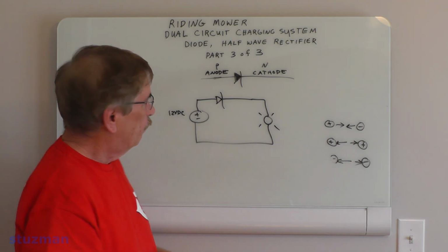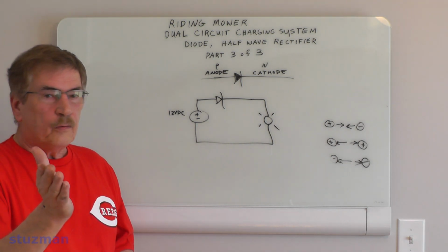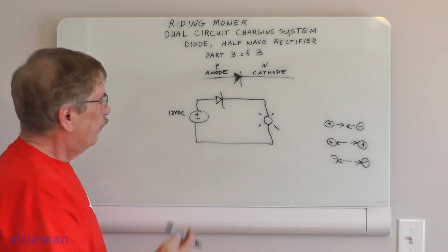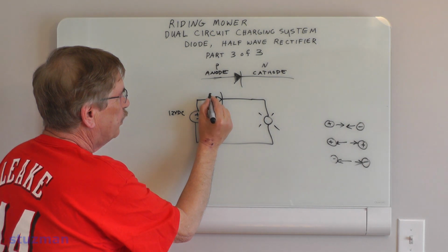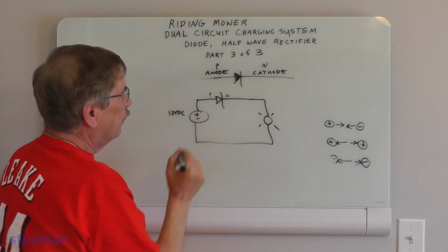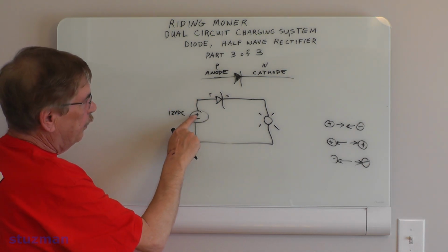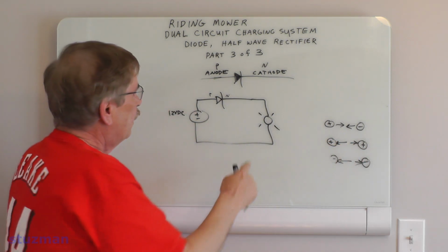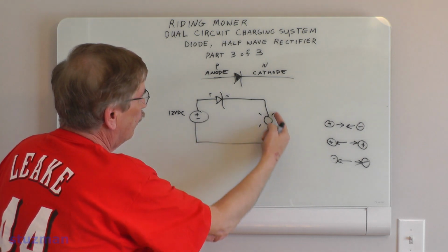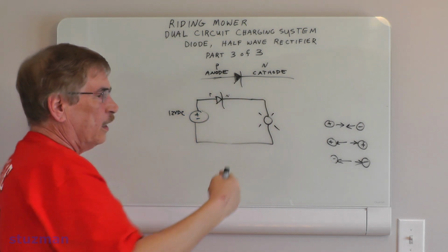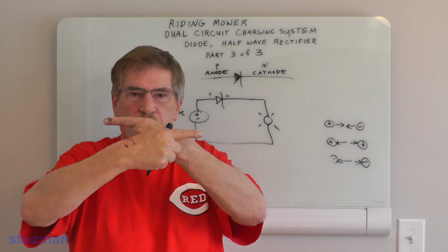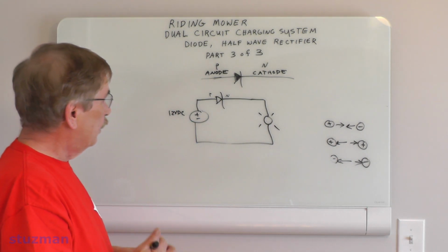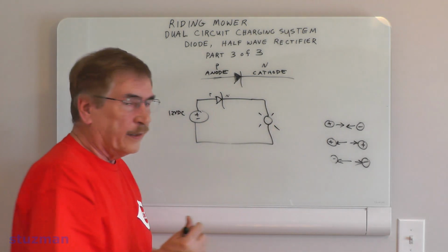All right. Now you can look at that. I know right now, is that diode turned on or is it turned off? Remember, here's our anode. Remember the anode is P. The cathode over here is the N-type material. Just follow it out. Positive charge, positive, pushing away. N over here, from the battery, pushing that way. So the two charges are coming across the P-N junction. That means this diode is turned on. All right? And this light bulb will light up.